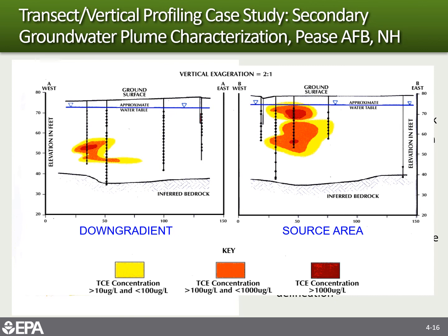And if we look at the source zone, B to B prime, and just down gradient, immediately within 2 transects, you have some understanding of what the plume is doing, and it's diving. So here we have higher concentrations located closer to the surface in the source zone, and as you move down to the second transect, just down gradient, you're finding that your plume has started to dive deeper.